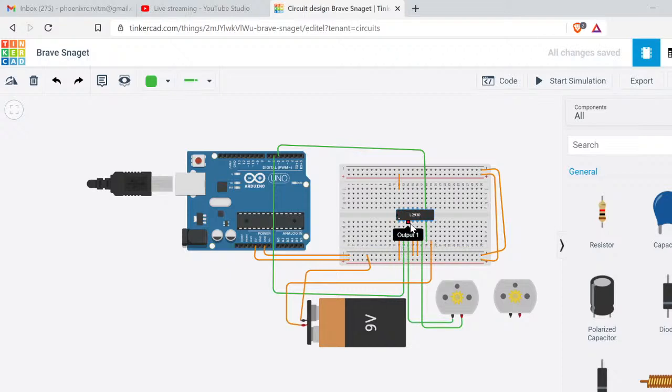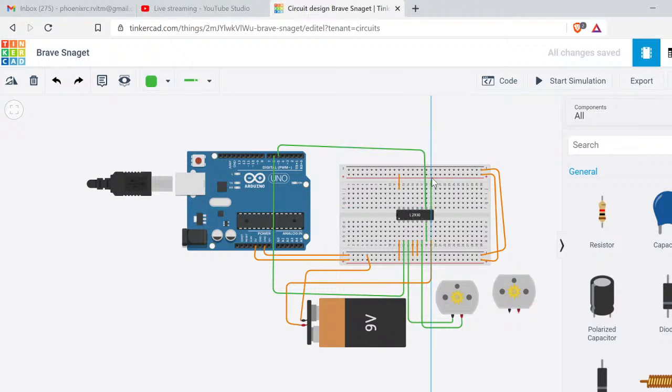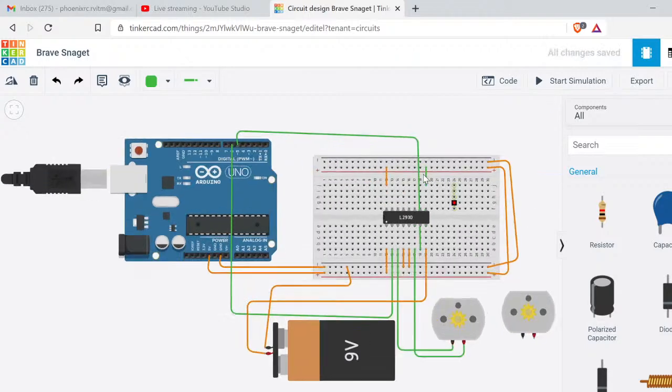I will not remove all the connections, because I am connecting this motor in a similar way. Here there are two power pins, one here, power 1, and the other at this one, power 2, and we are powering here and here. Now let's go to the enable pin. You know the enable pin is connected to 5 volts. Everything is the same, so I can just connect here.